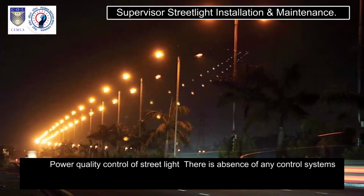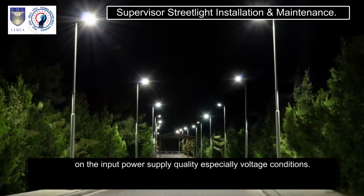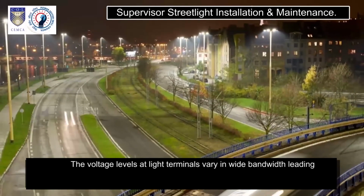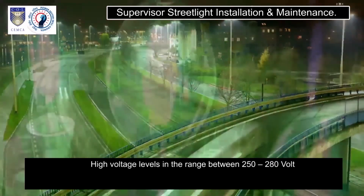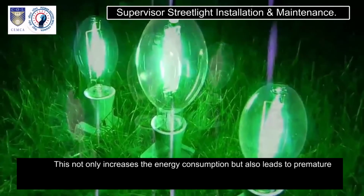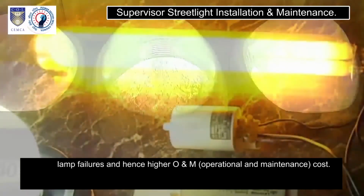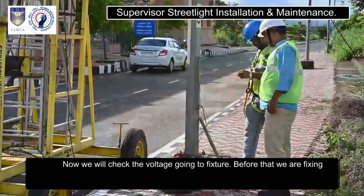Power quality control of street light. There is absence of any control systems on the input power supply quality, especially voltage conditions. The voltage levels at light terminals vary in a wide bandwidth, leading to high power consumption. High voltage levels in the range between 250 to 280 volt are not uncommon in the system. This not only increases the energy consumption, but also leads to premature lamp failures, and hence higher O&M, operational and maintenance cost. Now we will check the voltage going to the fixture.